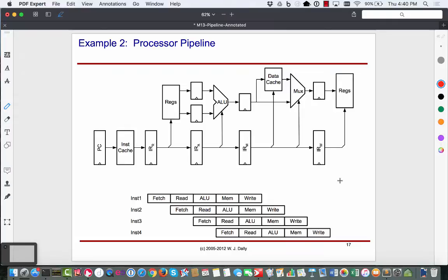So again, processors face the same issue. They can work on instructions in a pipeline fashion like this. They can also work on instructions in parallel, which is, they can say, let's fetch 4 instructions and start working on them in parallel. So both options are available, and they come with their trade-offs, and processors use both of them. Pipeline and parallel together is usually called superscalar processors. Within a processor, they will have multiple execution units so that they can run on each one of them.